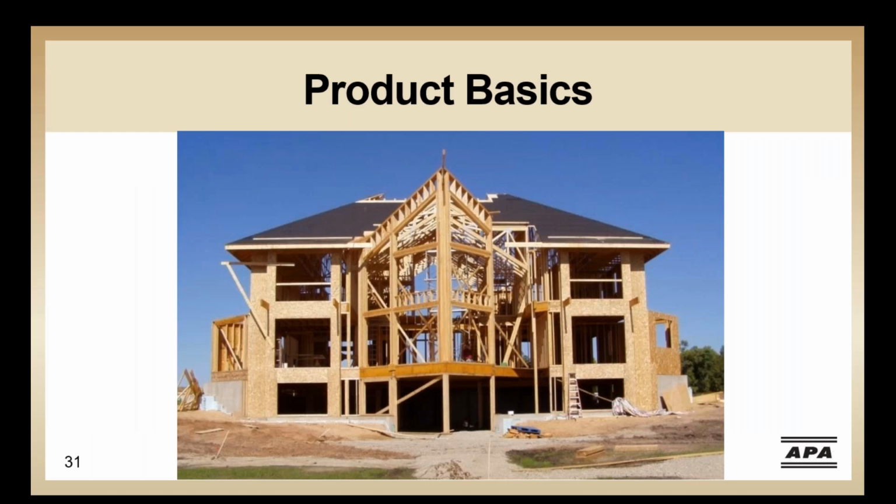Because of their availability in long lengths, glulam or SCL columns and studs can be used to frame multi-story wall systems to add both strength for the wall and ease of construction for the builder. I recommend you contact the manufacturer of these systems for specific design and specifying information. Some common applications, however, would be for great rooms and foyers of residential construction, with walls over 10 feet. This is needed when both vertical and perpendicular loads are equally important in the design of these walls, when wind loads need to be considered.